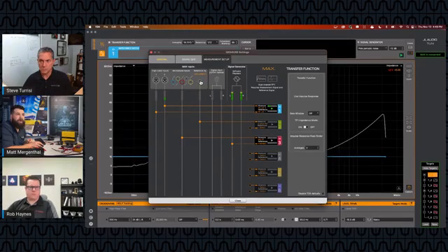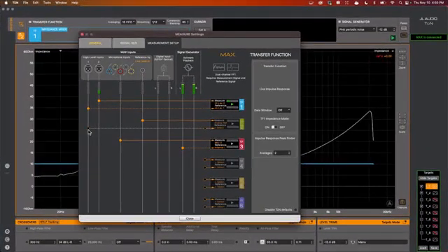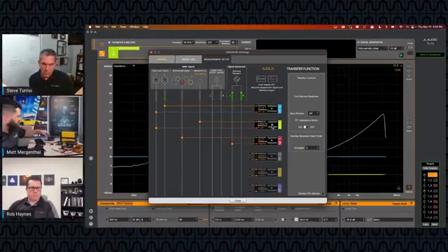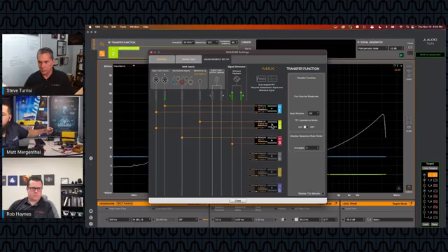right here. The default setting is internal analog loopback, so you may have to change it to external input. And then the reference would be the same reference signal, XLR number 1, that we already have selected here. So that's the signal that we're using, that channel of max to do that measurement. Then I'm going to go ahead and hit play, and I'm going to connect my other alligator probes to this probe here. Let me grab my